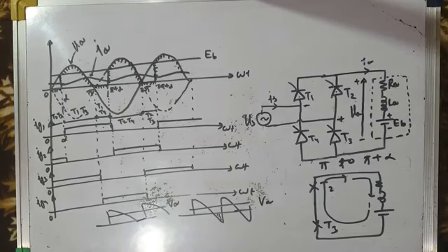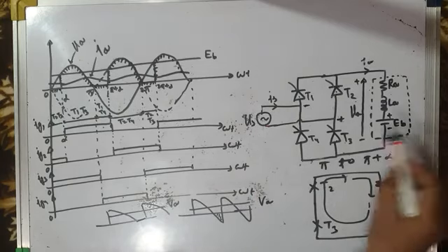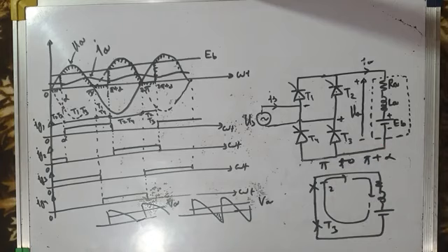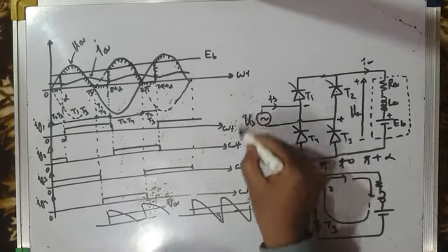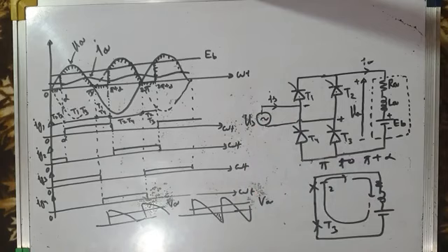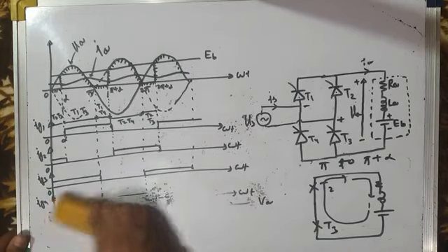Number one, there is no reactive power flow between source and load during the negative segments of the voltage because we have no negative segments of the voltage. We have cancelled those. Hence, the source side power factor improves. And secondly, since the negative segments of voltages do not exist, the average load voltage increases. So these are the advantages. So we can note down these two advantages.